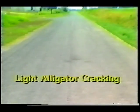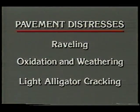Light alligator cracks are longitudinal cracks, about 1/8 inch in width, and usually occur in the wheel paths. These longitudinal hairline cracks are an indication of structural damage to a pavement. Frequently, pavements with only hairline alligator cracks do not have rutting associated with the cracks. These pavement distresses represent conditions for which asphalt chip seals are an effective maintenance technique.